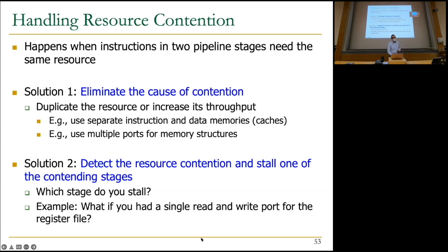Okay, so solution 2 is clearly not desirable with resources like memory and register file, because almost all instructions use these. All instructions use the memory, for sure. Almost all instructions use the register file. Not all instructions write to the register file, so you don't always have the write-read issue. But that's why solution 1 is employed very heavily for commonly used resources. If a resource is not very commonly used, you can use the second solution. So remember the common case principle of microarchitecture. Again, you can choose the solution based on that common case principle.